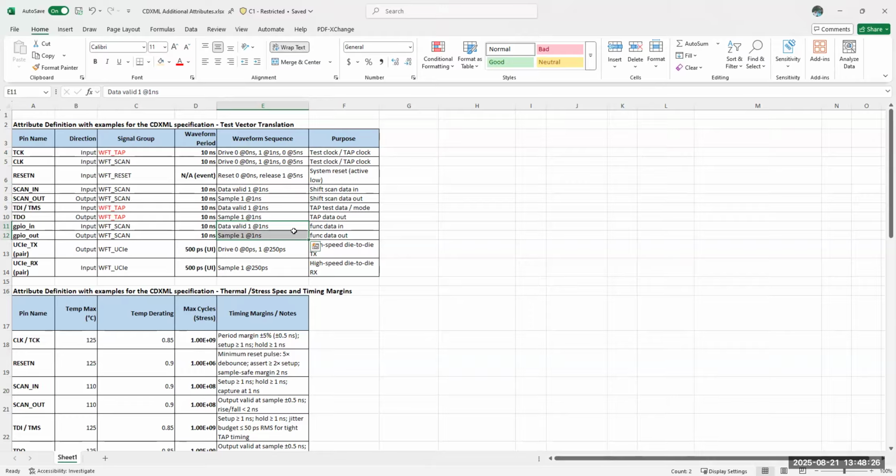They need to give some reference clock, and that reference clock for the translation tool is tied in the form of this attribute, so that there is no recovery or removal timing violation at the ATE itself when the pattern is applied on the tester. It is aligned to the respective reference clock. Okay.